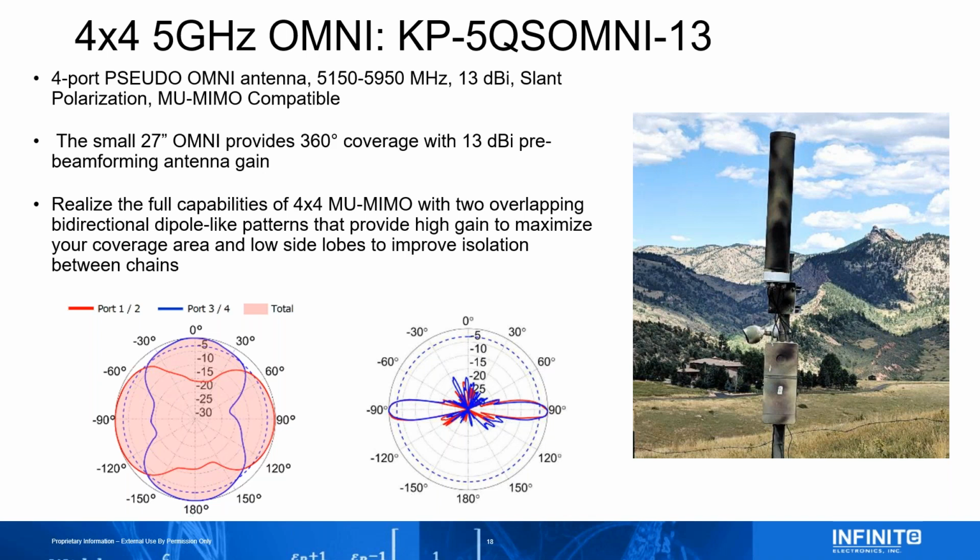You're able to serve a handful of clients with high data packages, and you can charge them a lot for it. And you want to be able to use multi-user MIMO on the uplink, so you can get that high throughput on the upside. So that's the ideal scenario: low density, but you want to charge them a lot of money. That's where I would use this type of package.